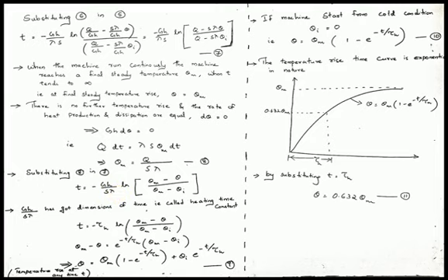So if you are trying to substitute the units of all this, and if you try to simplify the unit of this term, then you will be getting it as second, which represents it as a constant having the unit of time. So it is indicated as a time constant, which is represented as tau h here. So this relation can be modified into t is equal to minus tau h, natural log of theta m minus theta divided by theta m minus theta I,